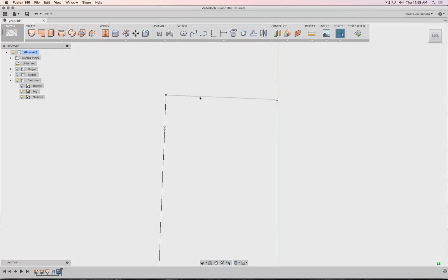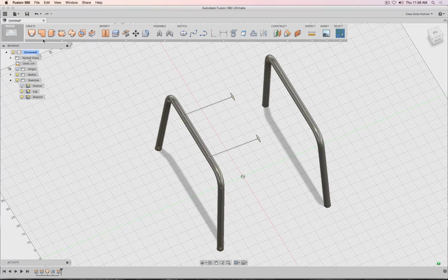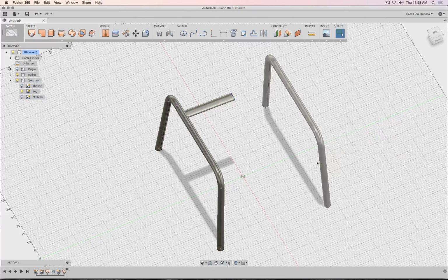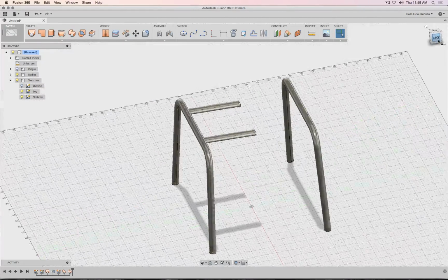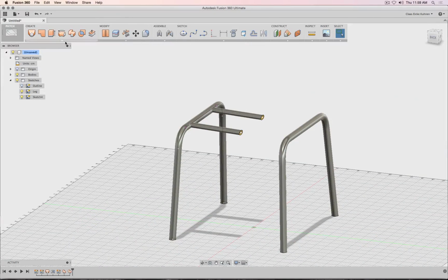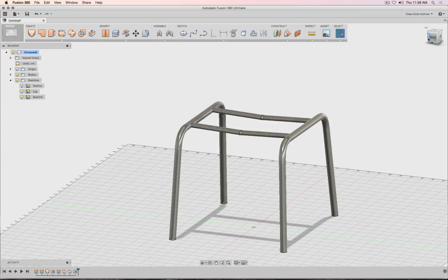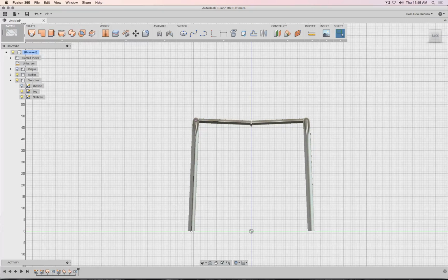And from this view you see the lines are kind of linear. So what I'm going to do now is use the sweep command. So sweep this one along this line. Okay. One more time. Sweep this one along this line. And then let's make a mirror for this one and this one along this plane. Okay. There you can see these pipes seem to be okay, but they're kind of pinched. And that would mean they would be welded together, because we can't make pipes this way. And that's a cost issue.